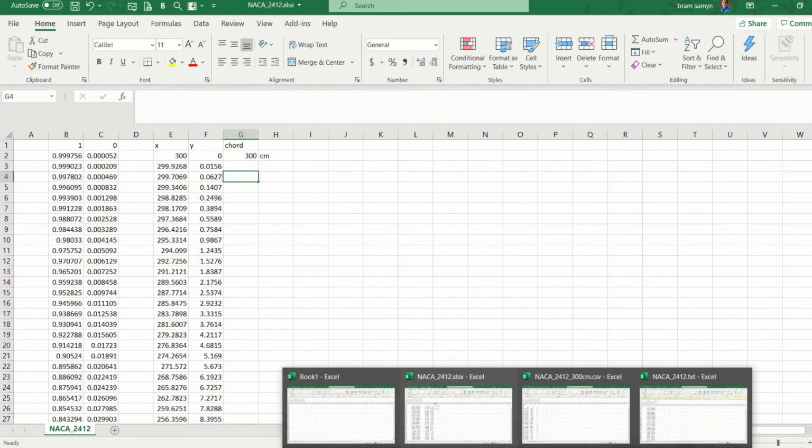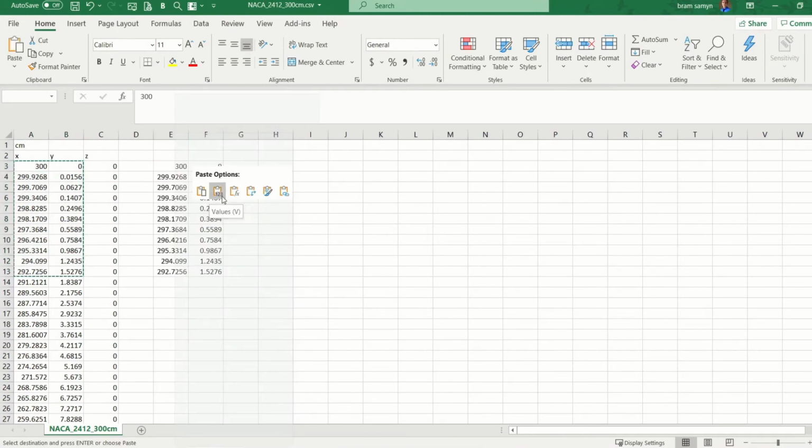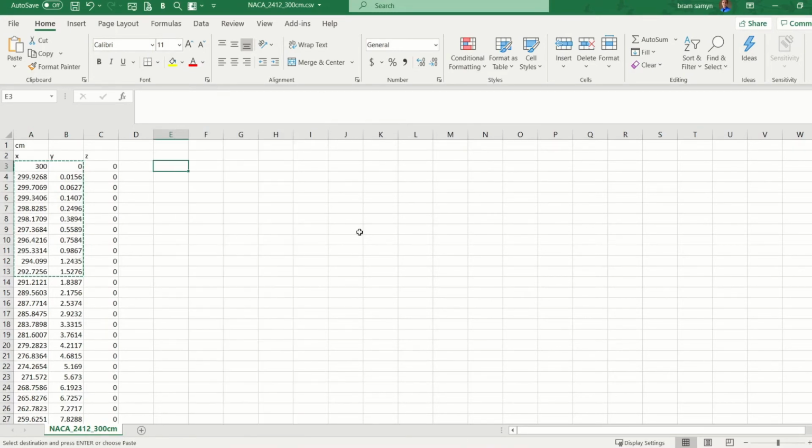Let's just give the example like this here, and you will paste them as a number or a value. This is what you will have to do. But note that if you don't define your z coordinates, it will give an error. So always make a column with z, and in case it's just a 2D sketch that you want to create, just fill it with zeros.